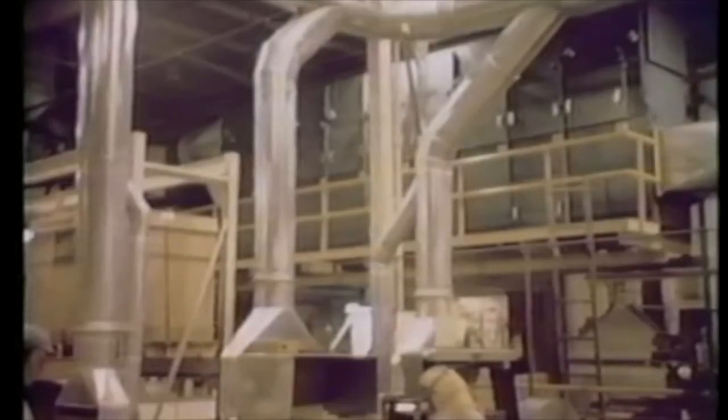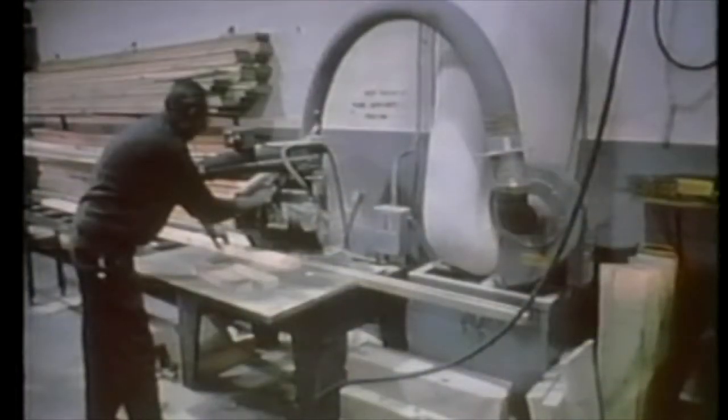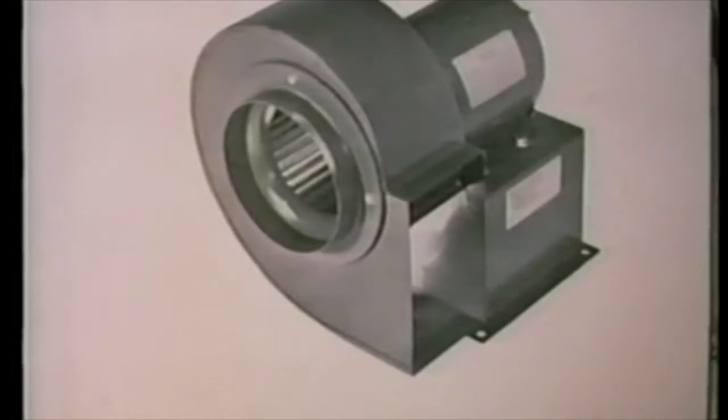Ductwork or piping transports the contaminants to an air cleaner or to the outdoor environment. Many local exhaust systems must be equipped with air cleaning equipment in order to meet air pollution requirements. The fan has to develop enough static pressure to pull a desired amount of air and contaminants into the hoods and through the ducts to the point of discharge. Finally, a stack is used to disperse the exhaust airstream and whatever contaminants get past any air cleaner installed. Let's look at each of these components in more depth.